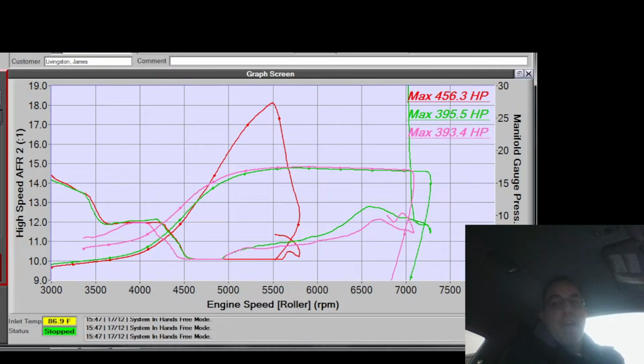So if I have a steady state current, it wants to stay at that rate, and if I've got to change it, the inductor's going to oppose that. If I have no current and I try and change it, the inductor's going to oppose that as well. So I can see what you mean by inertia. I just don't like that term in that one. But maybe, sure. Maybe more for the inductor than the capacitor. Inertia and voltage, I think is what you said earlier too. I'm not sure I love that one, but definitely resisting changes in voltage.